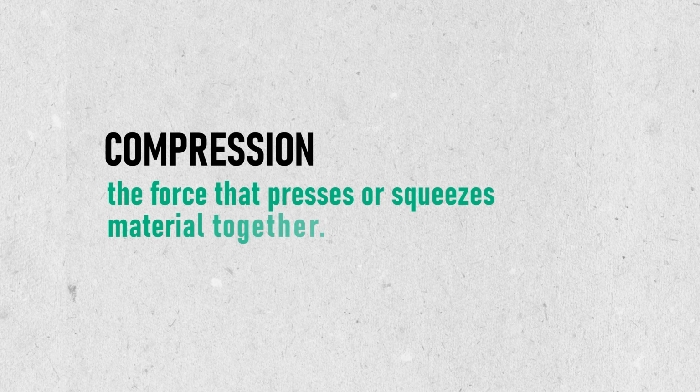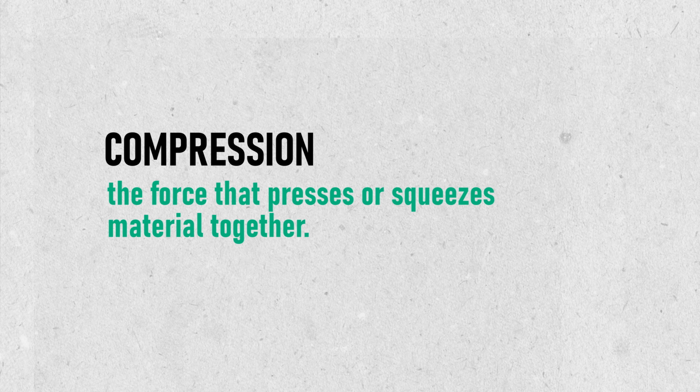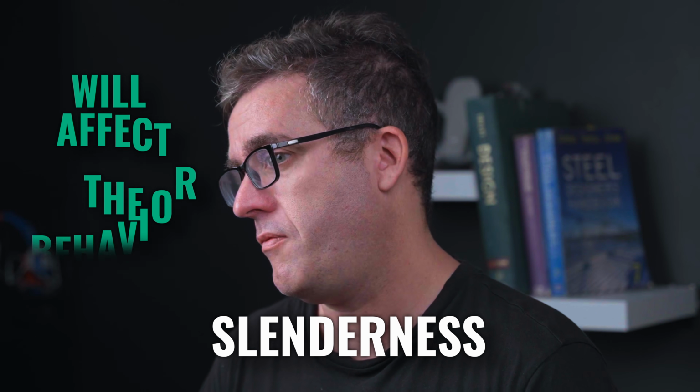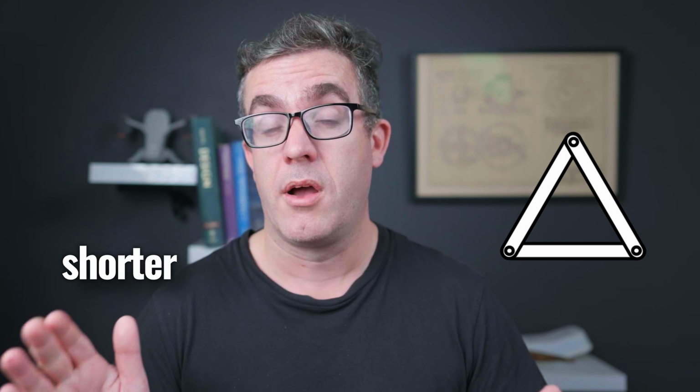So compression, when you're going down the basic principles of it, it's a little bit easier. You're just compressing that force. So when you've got a shorter section, it just holds until it either crushes or buckles. Now this is where buckling becomes a problem, because potentially the length of it and the slenderness of it will affect the behavior. So a more slender structure can take a lot less load. And we can see this when we apply stress to a ruler. You can see it bending down as the force is applied. Whereas if we go to a more rigid structure or a shorter structure and we apply that same compression force, it holds it a lot better.